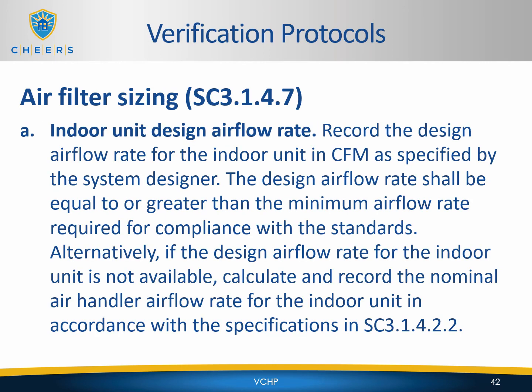Indoor unit design airflow rate. Record the design airflow rate for the indoor unit in CFM as specified by the system designer. The design airflow rate shall be equal to or greater than the minimum airflow rate required for compliance with the standards. Alternatively, if the design airflow rate for the indoor unit is not available, calculate and record the nominal air handler airflow rate for the indoor unit in accordance with the specifications in SC 3.14.2.2.